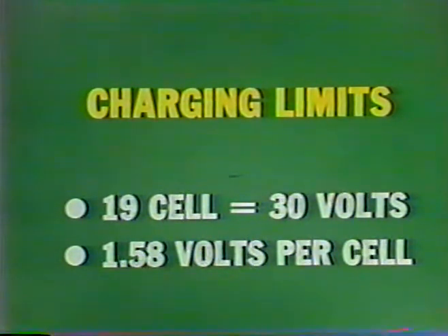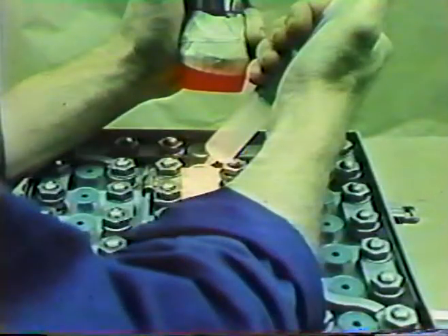If a constant voltage charger is used, it must be adjusted to the value recommended by the manufacturer. A battery is considered to be fully charged by a constant voltage charger when the charging current tapers off and stabilizes. When the battery is fully charged, its electrolyte will be at the highest level in the cells. Adjust the level as required, using only distilled water.